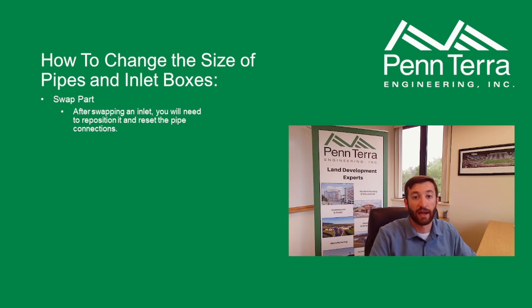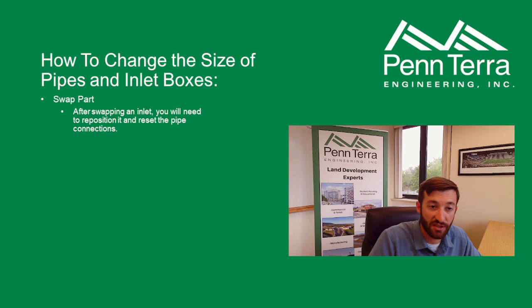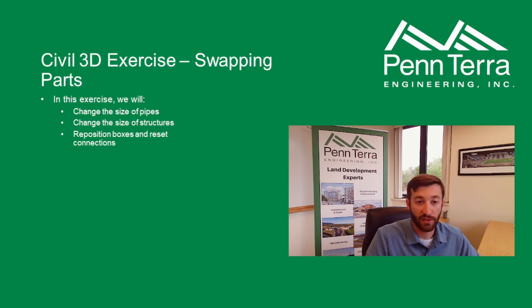Okay, next up, how to change the size of inlet boxes and pipes. So there's a command, it's called swap part. It makes it really easy. All you do is select the part, swap it, and then select the part you want to replace it with. The one caveat is generally you may have to reposition the box, especially if it's a type C, and you'll probably have to reset the connections on the pipes. So we'll jump into Civil 3D and I'll show you how to do that real quick.